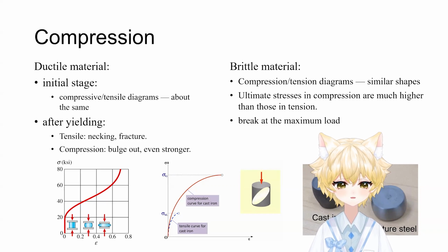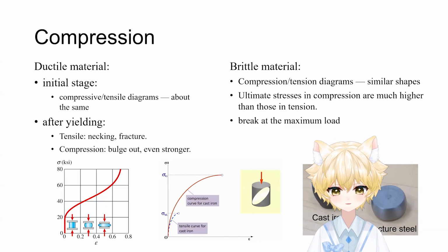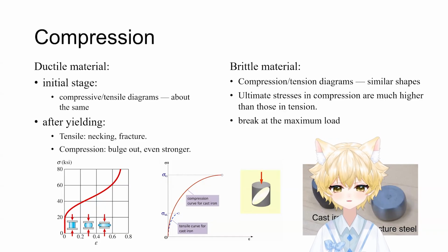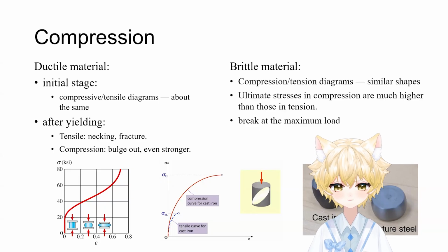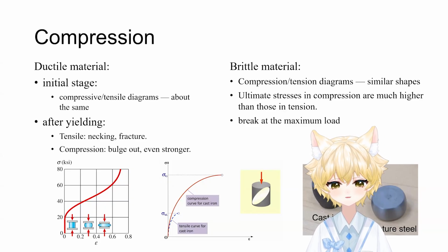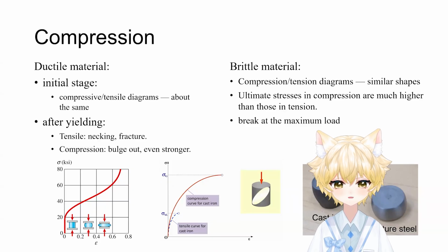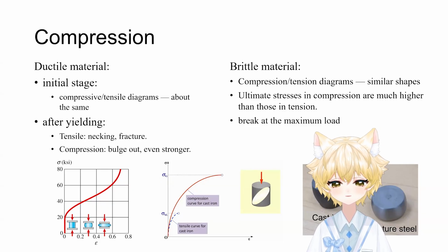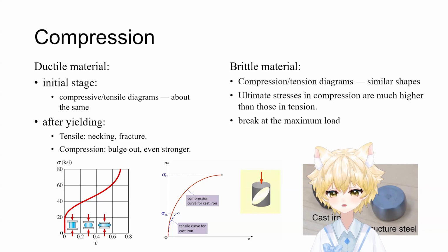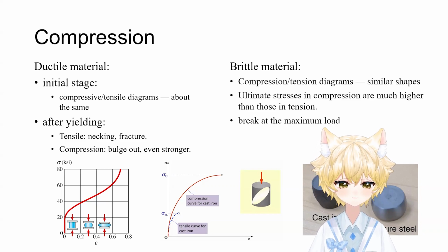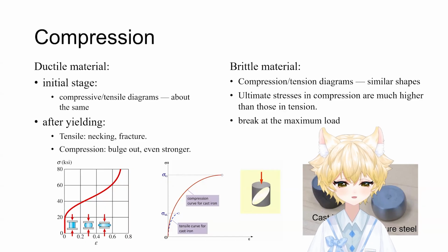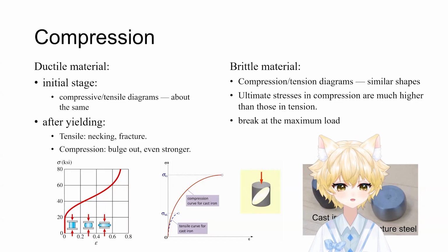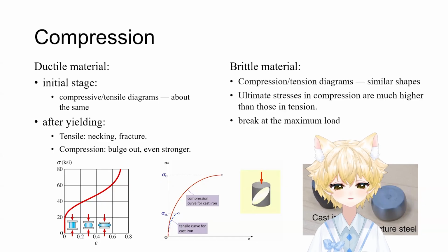Now let's look at the brittle materials. This is where the magic happens. In tension, these materials are very weak. They crack easily. But in compression, their ultimate strength is massive, often many times higher than their tensile strength. This is why we build foundations out of concrete and arches out of stone, right? We design the structure specifically so that the material is always being squeezed under compression and never being pulled, or tensioned. As long as we keep those materials in compression, they are among the most efficient materials we have.